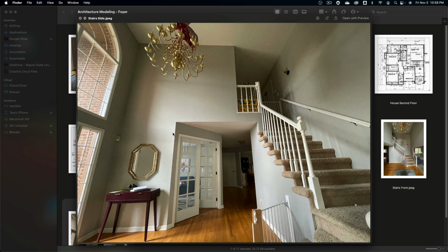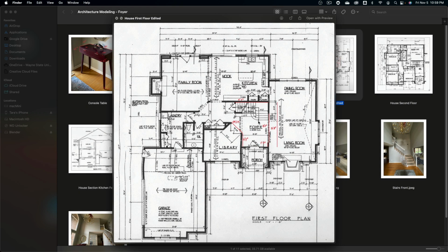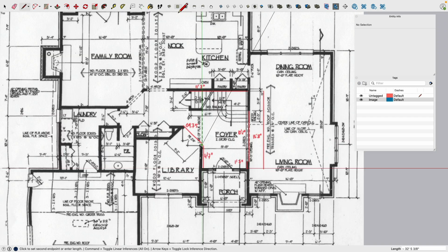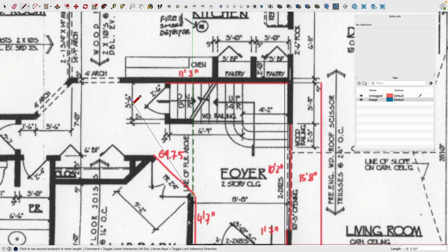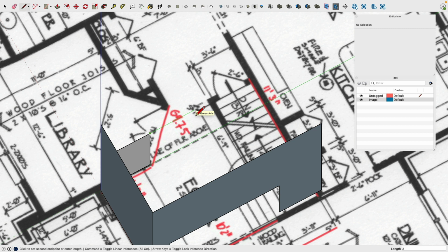So I need to have a line up, a line over, and then a line down again. I need to figure out how long this line actually is. I have not put this onto the image here, but I actually have this dimension here. So when we go into SketchUp, let's go into a top view, and there we see it. 3 feet 6 inches for the inside plus 5 inch for the wall is 3 feet 11. So along the y-axis, 3 feet and 11 inches.